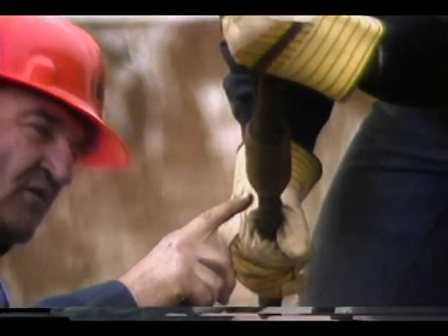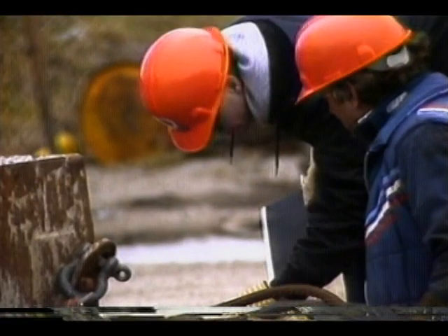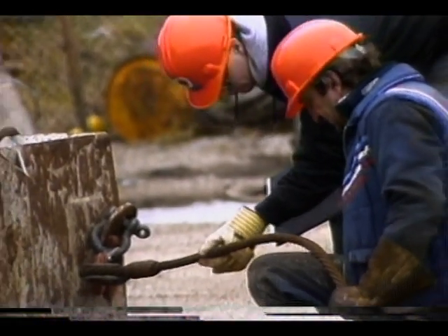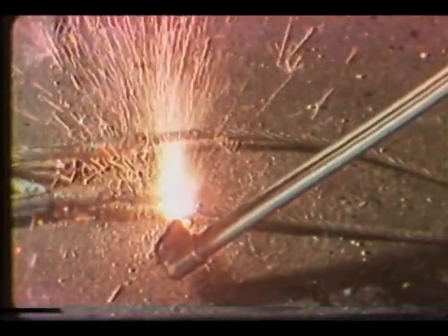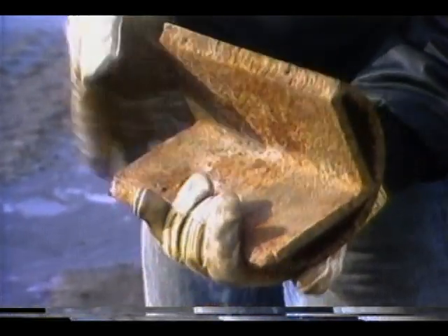Ropes should be inspected regularly, especially the sections subjected to bending, abrasion, and vibration. The rope should be taken out of service if there is any doubt about its reliability. Proper use and maintenance will ensure that wire ropes retain strength throughout their working life.